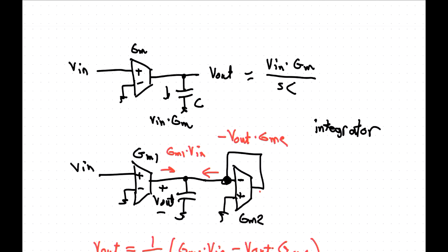No. If you have 3 poles, you probably want to put 1 on the real axis and then 2 as complex conjugates, and they are not necessarily going to be at the same frequency. It depends on what type of filter you want. If you want a constant phase filter, or a maximally flat or whatever filter, that depends on how you locate the poles, but not at the same frequency. Normally you put them as complex conjugate pairs, perhaps with 1 on the real axis. So they have the same real components?